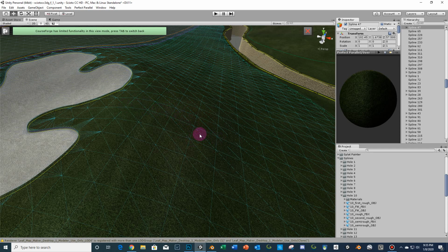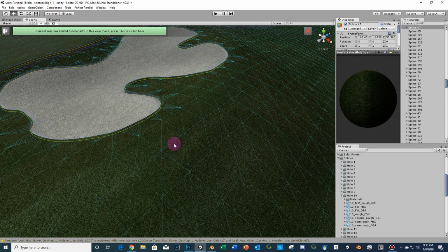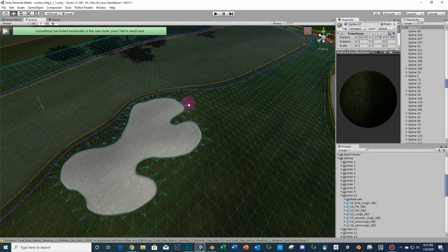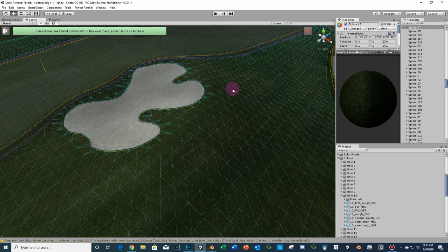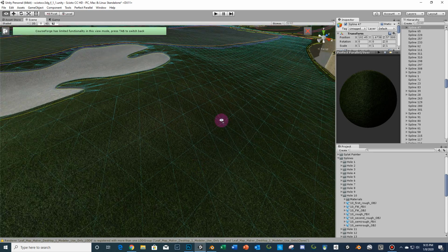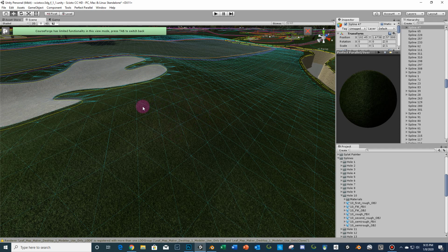So one thing I would suggest, and this is what I'm doing on my Oakmont, is you can actually create a detail layer of rough and put that around the bunker, and then it will create more triangles in this area, and when we take it into Blender, it will do a better job at creating the mesh, so that you'll have a good approximation of this curve.